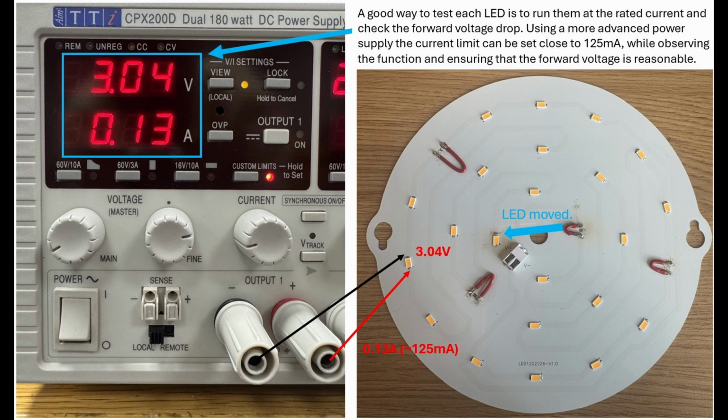So I used a constant current, or current limited, power supply, and I set the current limit to 125 milliamp, or 130 in this case, and then I let the voltage float. I connected each of the LEDs to the power supply, running 125 milliamp through each device, and checked whether I got the rated voltage.